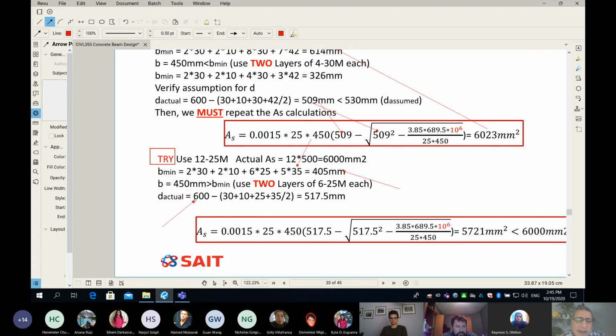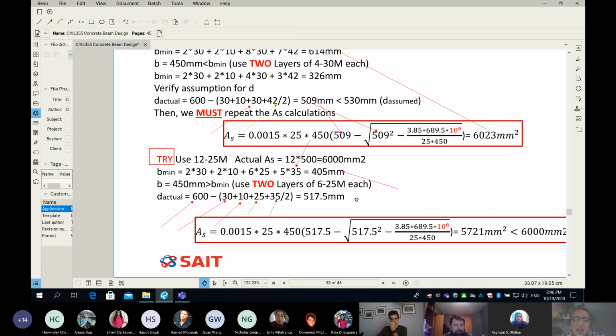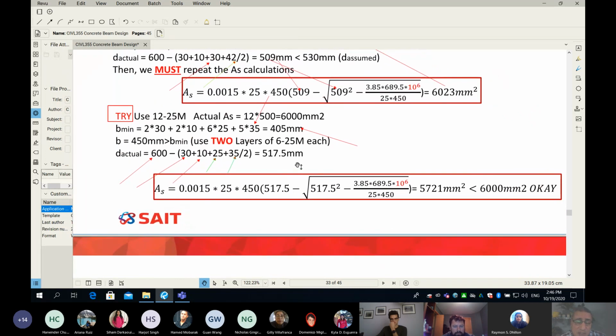Look at this. This is the same, doesn't change. This is the same, doesn't change. This one is the same, doesn't change. However, this one changes. Guys, please refer to this one as well. And this one changes. Let's color them. Let's put this one as, let's say, green, and this one green as well. Those numbers have changed: the bar diameter and the spacing. Please take a look at those numbers. Now you can see I got a different G prime and G actual.